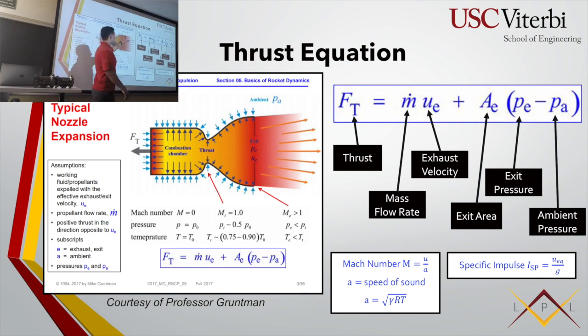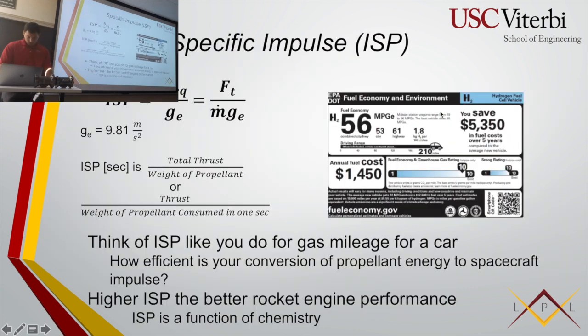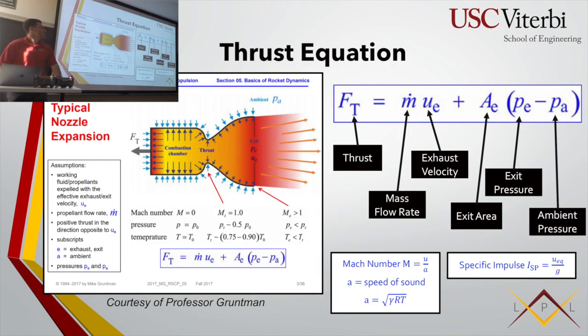But I believe that if this ends up not being optimal, this will be lower, and so essentially it'll not be as high of a thrust as if it was equal to each other. But when it is equal to each other, this goes away, right? This becomes 0, so this whole term goes away. And that's why a lot of the times you'll see equations that say thrust equals m dot times UEQ. Yeah, and that's actually why, because U equivalent actually equals UE plus this.